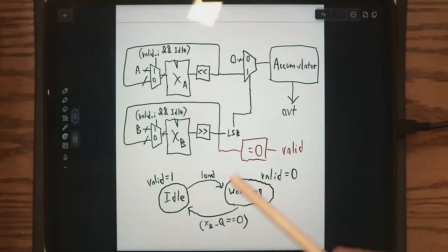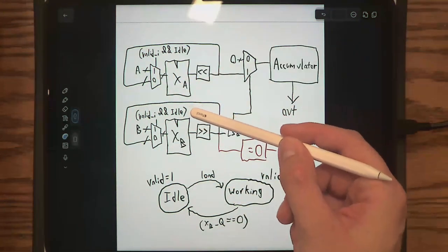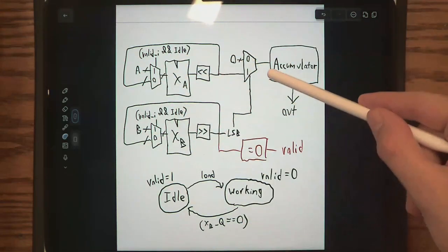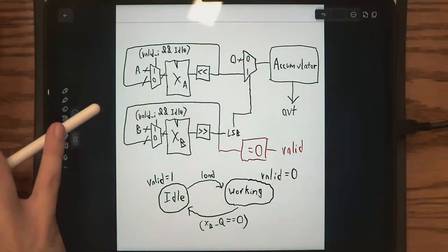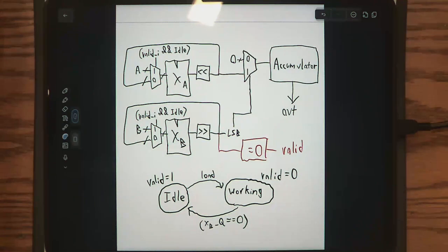Ready, yeah. So this circuit should probably also output a ready signal. And if you have the case where this circuit is both receiving a valid signal and at the same time sending out a ready signal, meaning this circuit is broadcasting that it's ready, and a transmitter is sending in valid data, if there's both a ready and a valid at the same time, then that is a guarantee. It's a handshake that there must be data flow at that time.